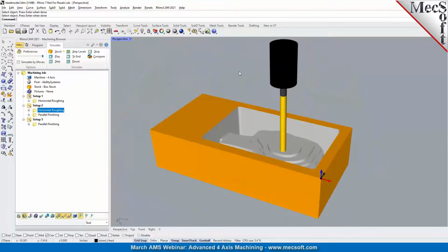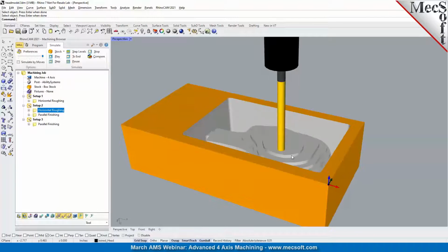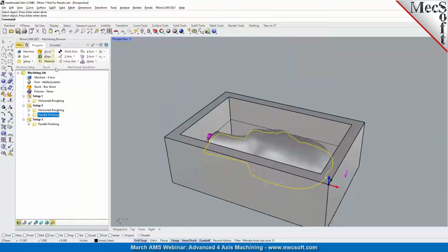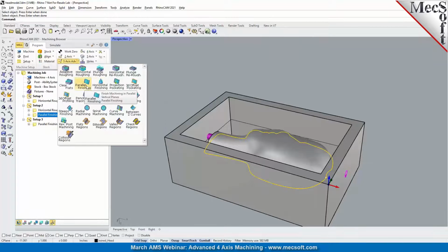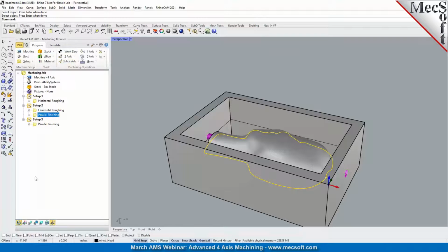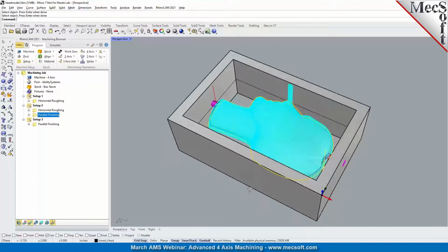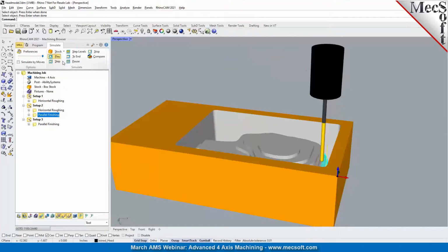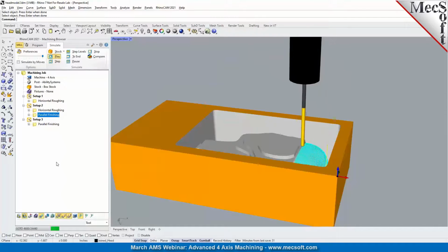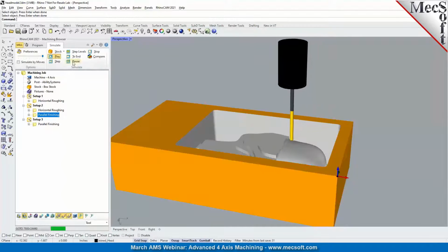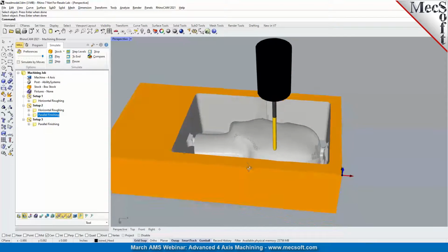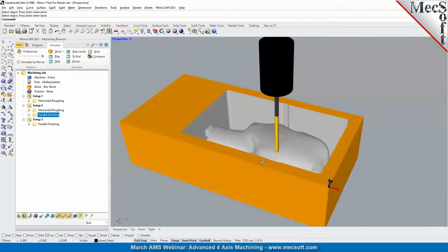Now, once the roughing is completed, we could go into a pre-finishing and a finishing operation. So we will program a parallel finishing operation from the 3-axis methods. I'm just going to use one of the operations in here, a 3-axis parallel finishing. And let's go ahead and run a simulation. It's also known as index machining, could be 3+1 machining, where you can do a combination of 2 and 3-axis operations in conjunction with rotate table setups.